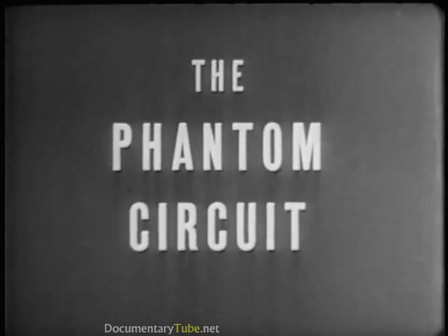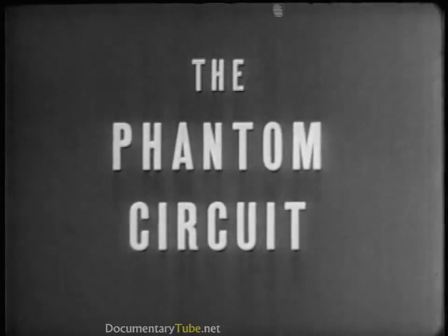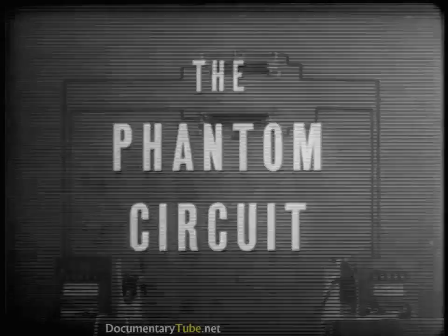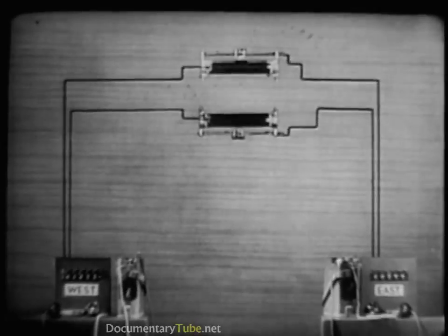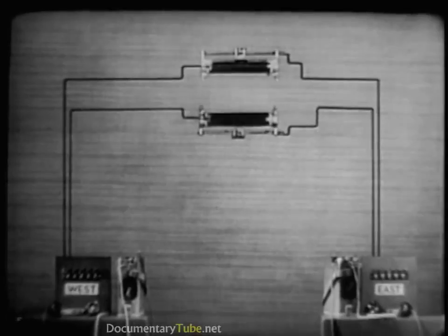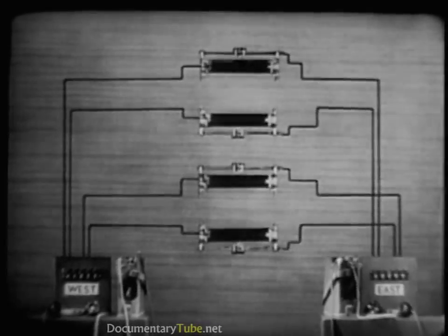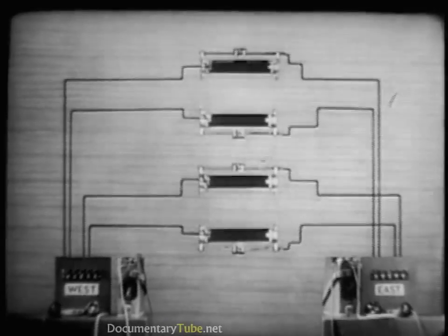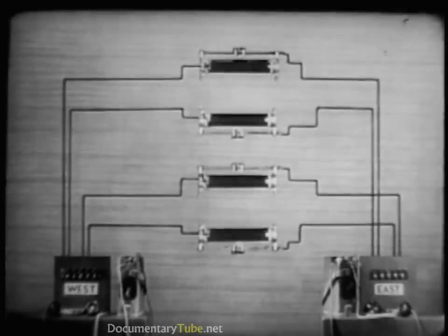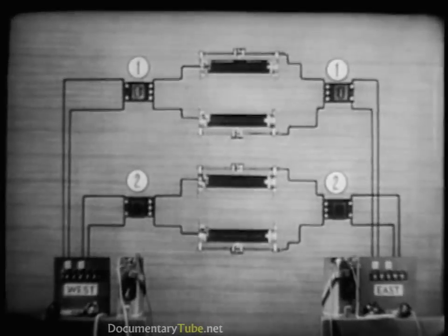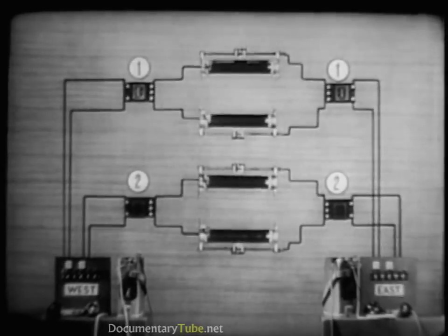There is another way to get a good extra channel cheaply and without the disadvantages of a ground return. This is to install a phantom circuit. The phantom is similar to the simplex. Instead of using the telephone circuit and the earth, however, it uses 2 telephone circuits. The first step is to insert a repeating coil at each end of each line.